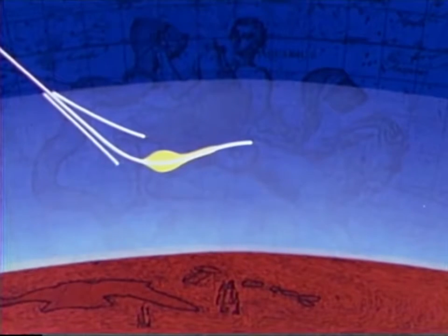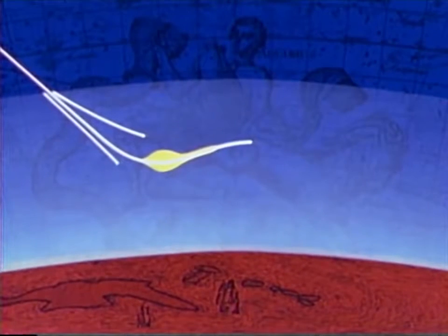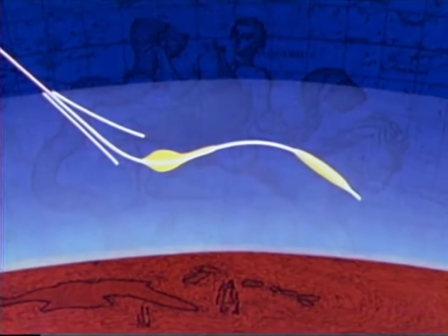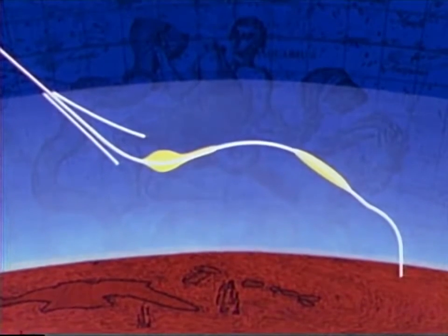As the skip is approached, aerodynamic control is reduced to practically zero. During the skip, the crew will be experiencing weightlessness. The skip will not take the command module beyond the 400,000-foot level. It will then descend, starting its second entry, and go on to the second control period. The entry phase is terminated at the 23,500 foot level, at which point the drogue parachutes are deployed and the spacecraft is committed to its landing point. We will now examine the entry trajectory in detail and see what occurs during each portion.